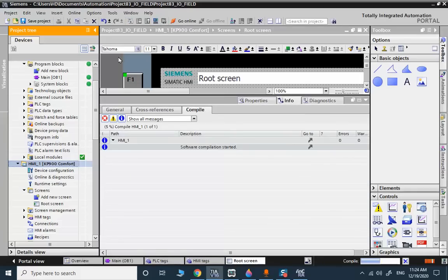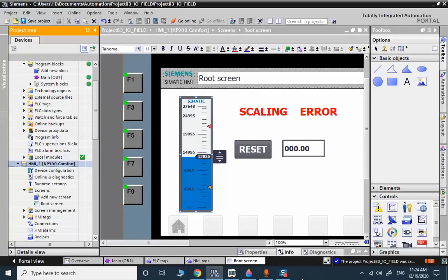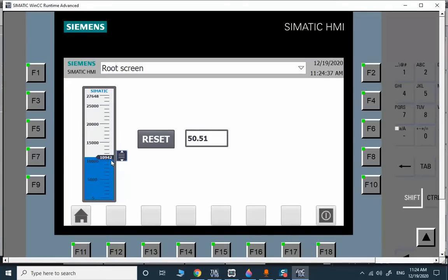When we have the negative value, it's somehow like the under range in a real transmitter. So in the positive case we have the positive values, and in the negative case, this is the safety of the system. It means that in the negative analog input, we have under range, and we decide to report the max value.